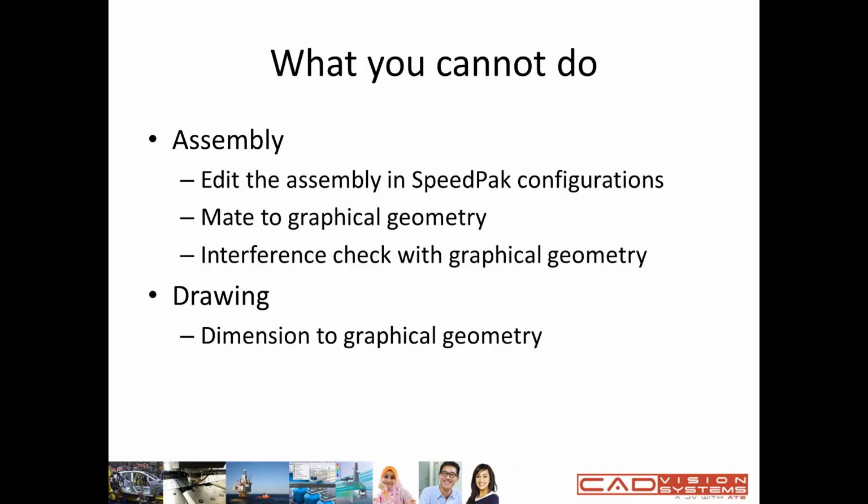Now we come to what you cannot do. In assembly mode, you cannot edit the assembly in SpeedPak configuration. You cannot do mate to graphical geometry. You are also not able to do an interference check with graphical geometry. Same in drawing as well: you cannot do dimension to graphical geometry.